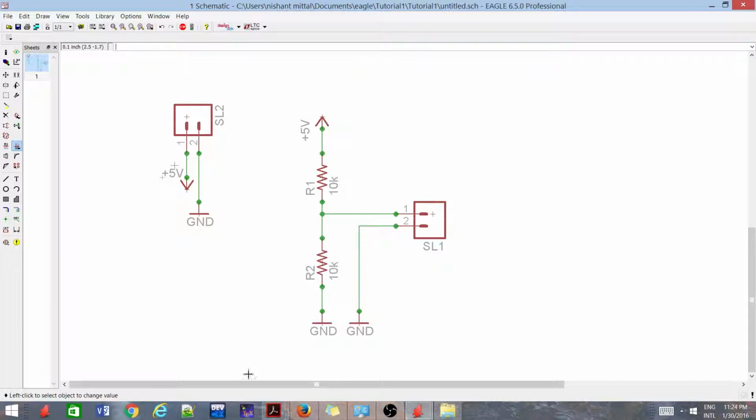So these schematics were created using the libraries from here. They were added and then they were connected using the wires. By using the junctions, we ensured that all the connections are intact and all the nets are connected as per our requirements. By clicking the smash button, we simply divided the names from my components and switched them to locations as per my wish.